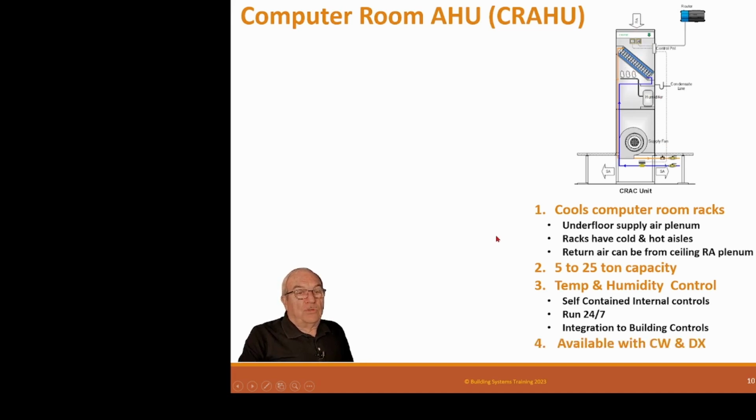Okay, available with chilled water and DX. So you can get one that's got this chilled water coil, but also has a DX coil in it for standby or backup, and then it goes out to a condensing system.